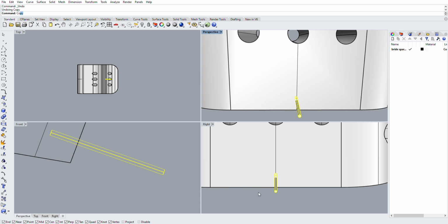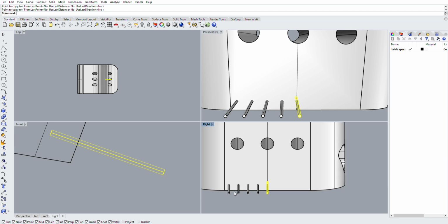What I'm looking at here is I'm running into the same thing. When I had them spaced 1.25 inches, the rivet was on the line for the bend. Now, I already know that my flange won't be there, so I'm trying to space out rivets to where they don't end up on the bend. And I'm just trying a few different spacings. I end up spacing these 1.125 inches apart, I believe. It's weird voiceovering because the little screen on my phone here is too small for me to see my actual measurements. You'll know, and I don't at the moment.